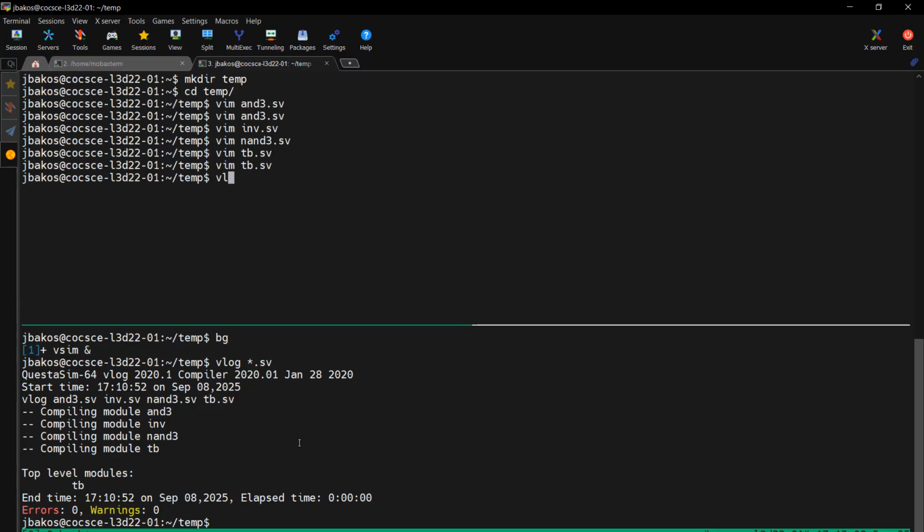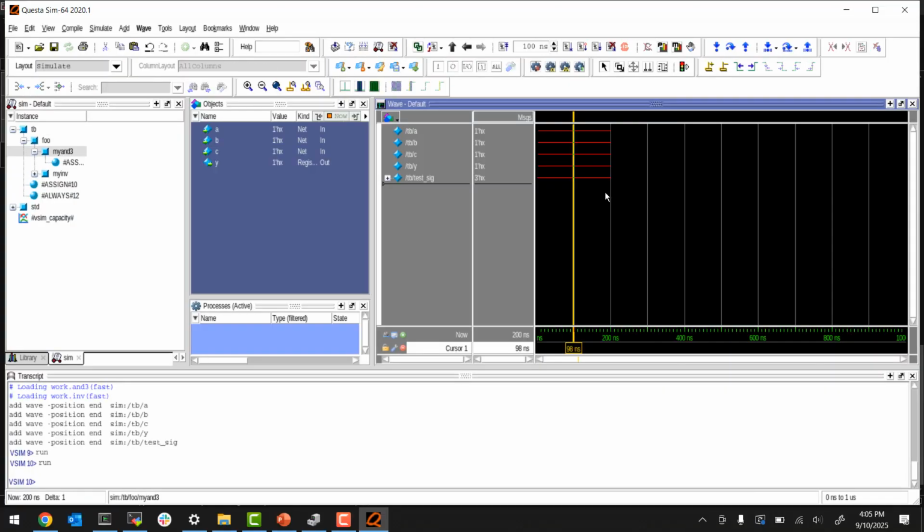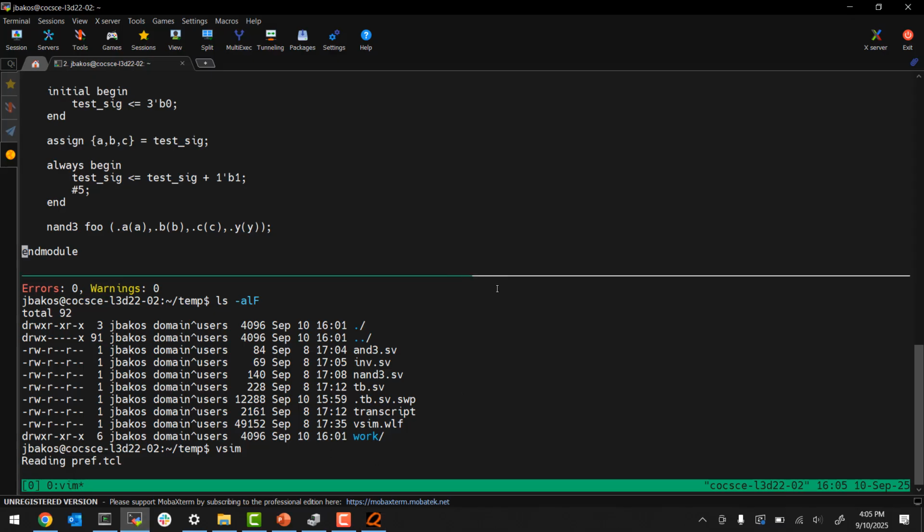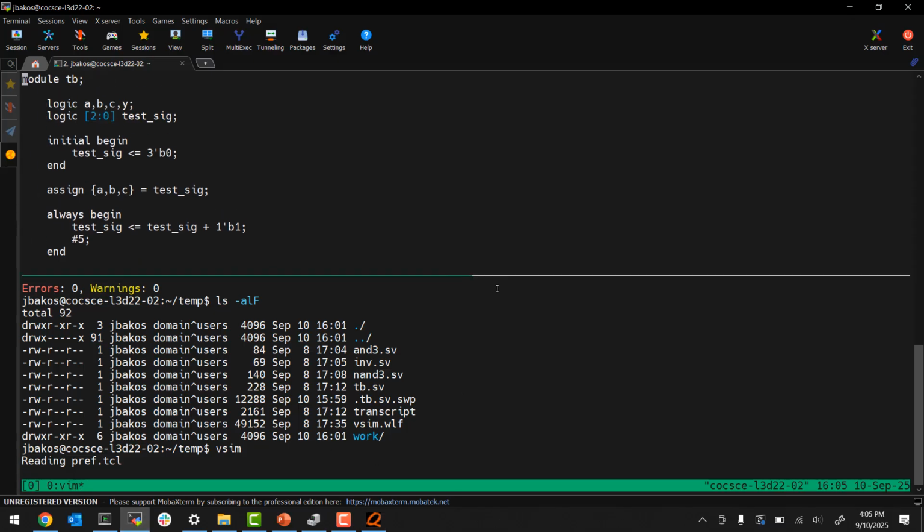All right, vlog *.sv. You can see that we have X's here, so that's a bad thing. Remember, X is one of the 4 states of logic you have in Verilog. Also, you'll notice that A, B, C, and Y are all 1 bit, but this test signal is 3 bits. I'm sure you can't see it in the back, but it says 3 there.